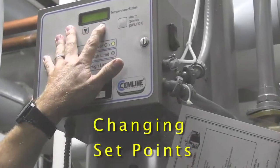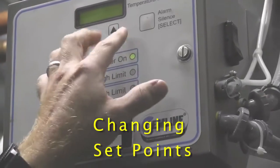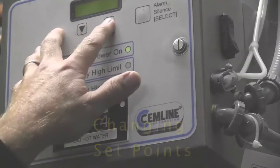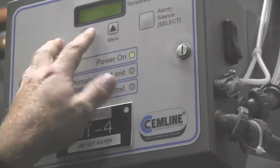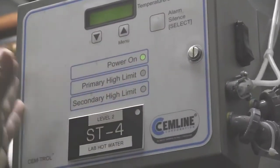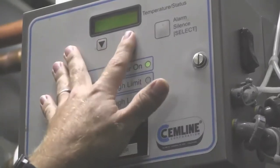First thing you do is you hit your menu button 1 time. It gives you your set point. If you wanted to change your set point, you then hit the enter button. Then you would change your set point by using the arrows, and again hitting the select button. If you don't hit the select button, it will not save your settings. So your set point number 1.